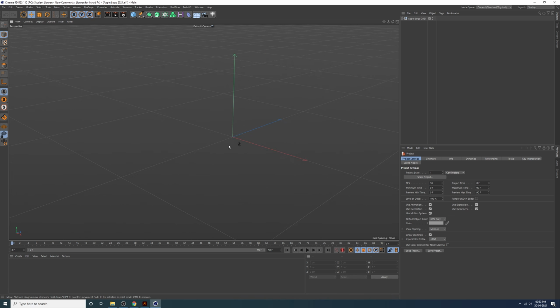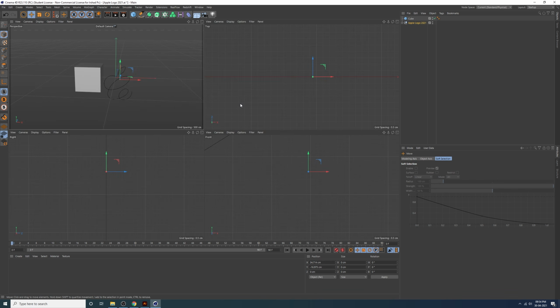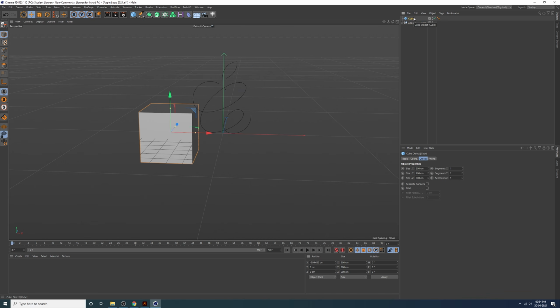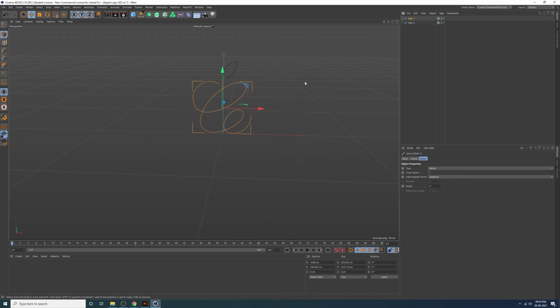So you can see your spline and the shapes here, but it's very small. I just create a new box to compare the size, then select the shapes and use the scale tool to scale them. If you press the middle mouse, you can access these four windows. Then go to front view and adjust. That's all. Anyway, we just delete this box and drop the shapes to the bottom. We just need path 1 and path 2.